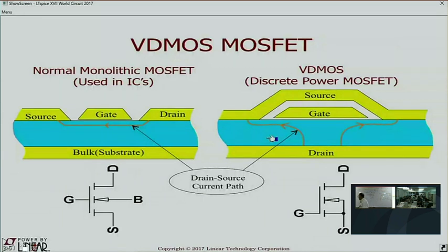Now here it looks like it might just be a little detail, but no, this is all basically conducting, so basically all of the dielectric between the gate and the drain is due to the channel when it's off. The gate drain capacitance changes by about a factor of 3 to 5, depending on whether the transistor is on or off. That's a huge change in Miller capacitance, and since it is the Miller capacitance that determines the switching characteristics of this transistor, you can't use these device equations to describe the behavior of that. That's the problem.